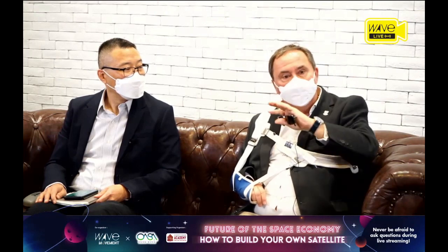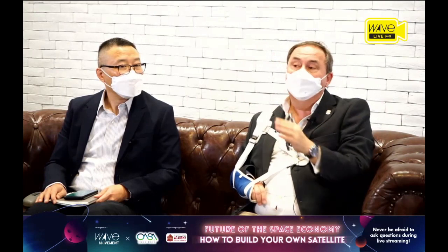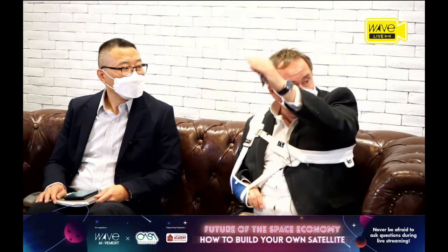But at the end of the day, each CubeSat has something called a payload. The platform's a CubeSat, the payload is what the CubeSat actually is designed to do. Now, R1, which we're going to be developing from next year, we hope to launch it within 2.5 years, is a 6U CubeSat. So it's 3 of those 10 by 10 centimeter elements down and 2 across, so it's 6 altogether. 2 of those are the payload. That'll be the gamma ray telescope.